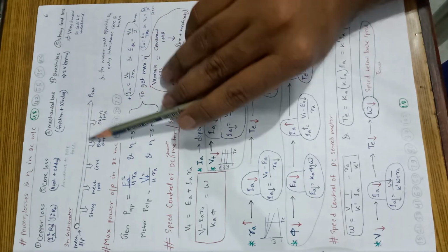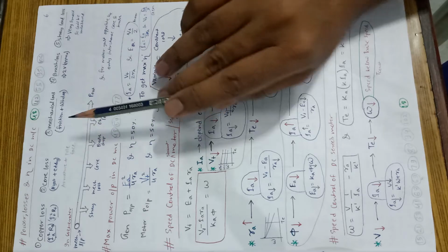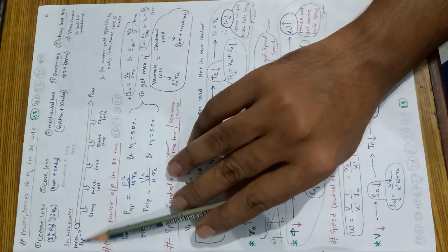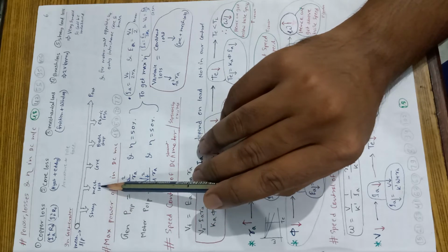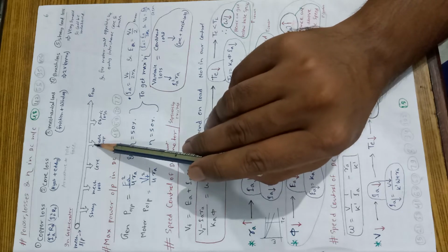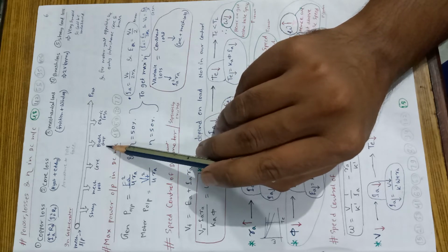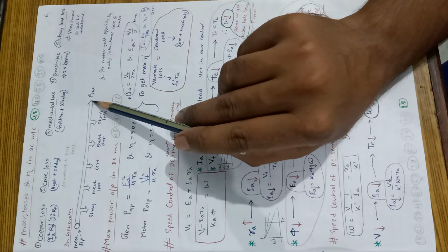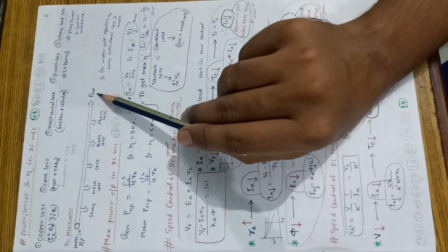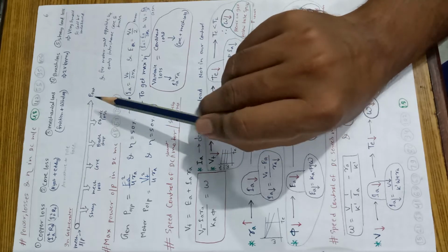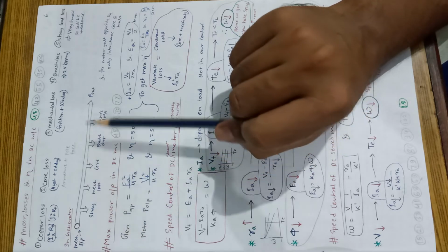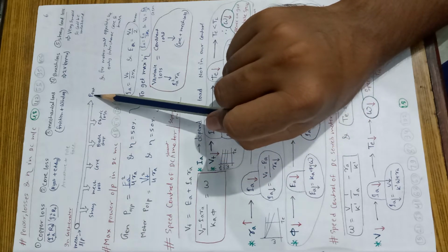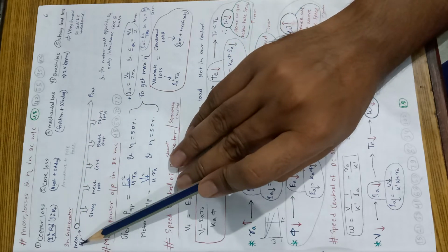When we talk about the power flow diagram of a generator, first we give the mechanical input, then stray load loss is subtracted, and then mechanical loss, after that core loss, and then brush drop loss, and then ohmic loss, and finally we get the power output. For a motor, we just go from the opposite side. The power output is mechanical, and the input is electrical.